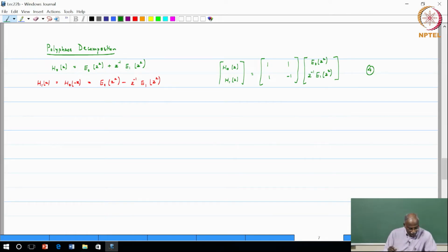Okay. Now I want you to write down for me the synthesis filters. So very quickly let us just pencil them down and then write it in matrix form. F naught of z, from aliasing cancellation principle choice, h1 of minus z. So that is straightforward. h1 of minus z is actually equal to h naught of z. So f naught and h naught are one and the same filter, because of the polyphase decomposition, the QMF constraint, they actually map back to the original one.